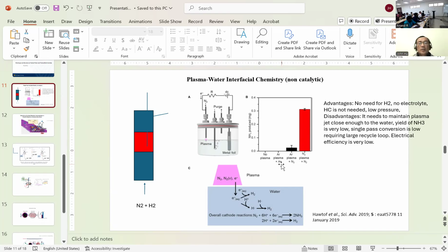Yes, it's going to be more efficient if you heat up the water to a certain temperature, but you don't want the water boiling because you have steam coming out. It's an open system because the nitrogen comes in and then the purge gas comes in and purges out. So you probably can heat it to 80, 90 degrees C. Don't let even that steam vapor come out. But yeah, good approach.